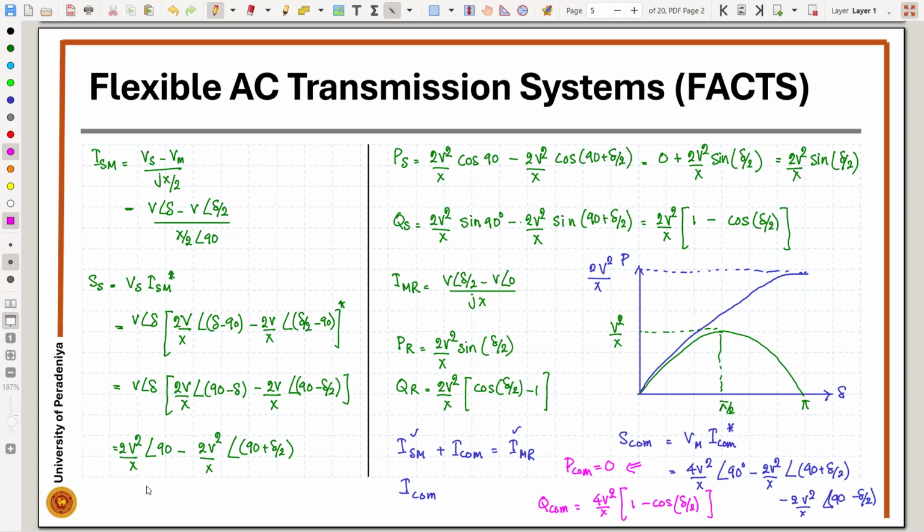Well, it depends on the requirement that we have. That's why I mentioned that this can be used in a place where we would have under voltage issues, and we can also use this in an over voltage situation. Over voltage means the light loading condition, under voltage means the heavy loading condition. So depending on the problem that we have, we have to select what kind of compensator we need. In some places it can be a capacitor, in some cases it can be an inductor.